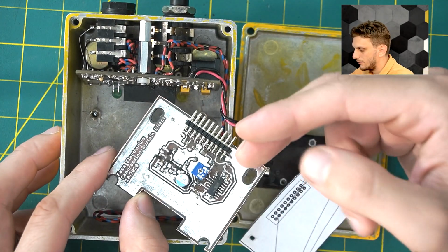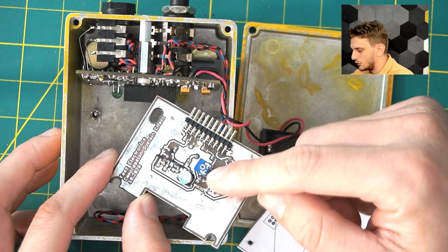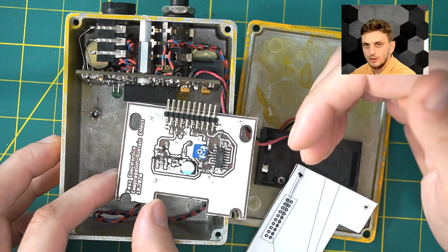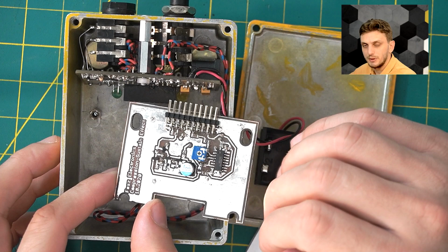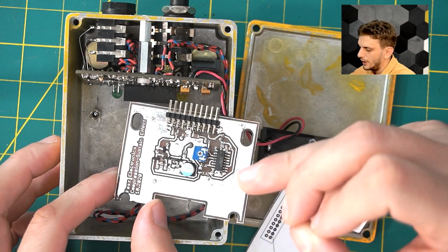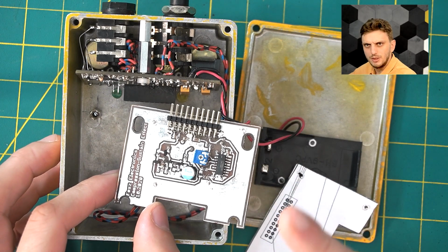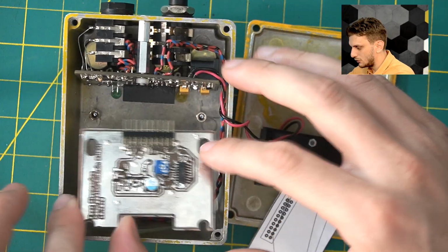And we can notice our two large components. So we have our variable resistor and also this huge capacitor. Now this is not the 10 microfarad capacitor that we saw in the schematic, it's an 82 microfarad capacitor. And it's not a normal aluminum electrolytic, it's a polymer electrolytic. Basically, this type of capacitor has far lower ESR, and we'll see why that's important in a moment. But for now, let's just see how this thing fits into the box.